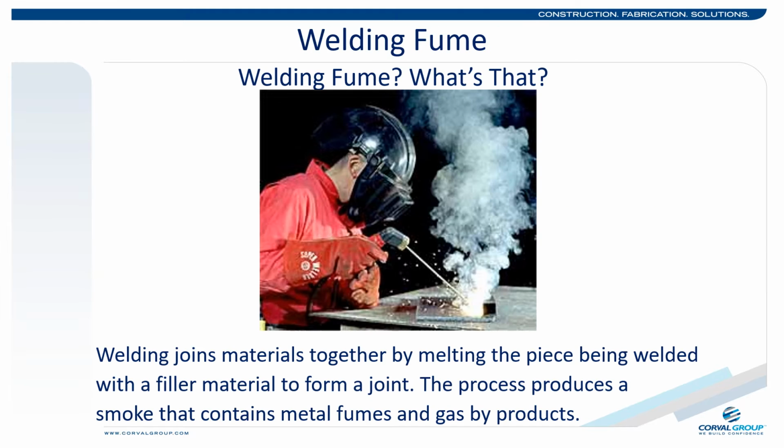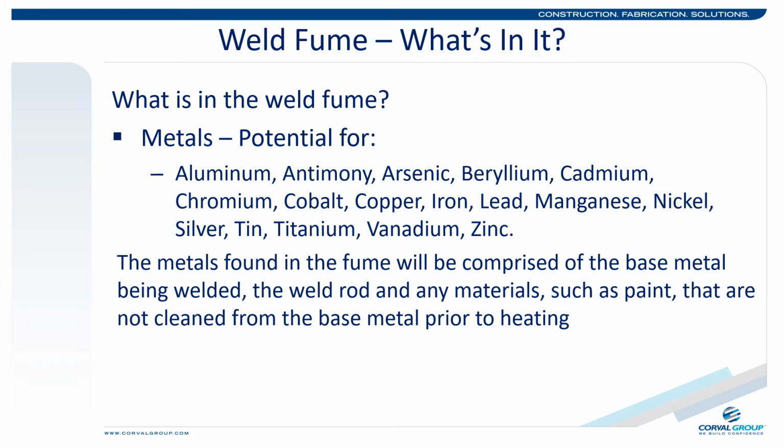What is welding fume? Simply stated, weld fume is the smoke that is produced when welding. The smoke contains metal and gas byproducts that have the potential for unhealthy consequences. A good question to ask when assessing the hazards associated with weld fume is, what's in it? The fume, in all cases, will contain metal particles of one kind or another. The potential exists for various metals based on the material being welded, type of rod being used, as well as compounds found in any paint or other materials that may be left on the base material.